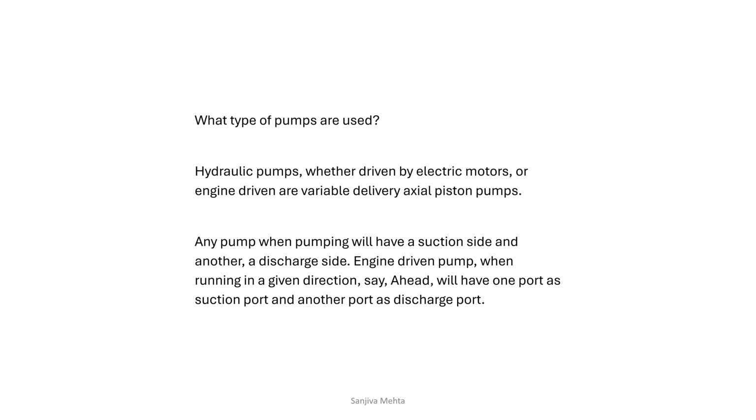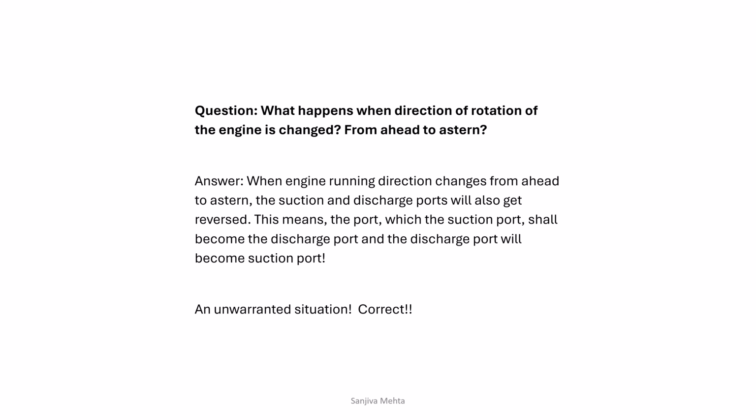In unwarranted situation, we don't want that. So what to do? What happens when direction of rotation of engine is reversed, changed from ahead to stern? When engine running direction changes from ahead to stern direction, the suction discharge port will also get reversed. This means the suction port will become the discharge port, and the discharge port will become suction port.